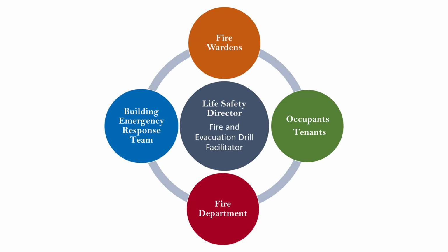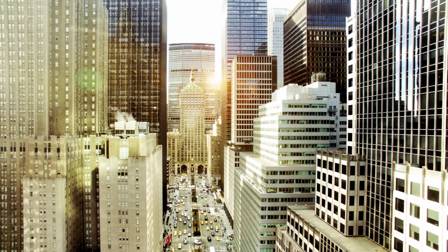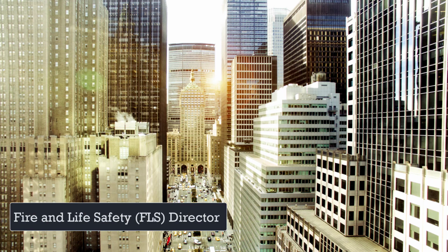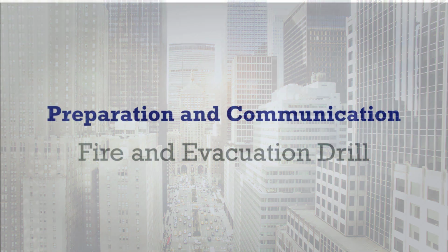The building life safety director position should be designated in writing and held by an experienced facility owner-manager representative. The facility manager, operations manager, or security director are best suited in this essential role. In select jurisdictions, for example, New York City, appointing a fire and life safety director as a primary responsibility is a city code requirement.